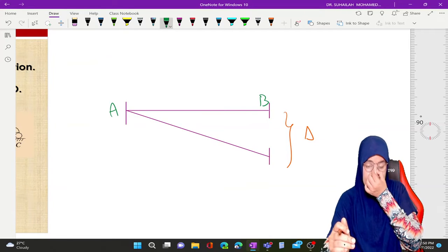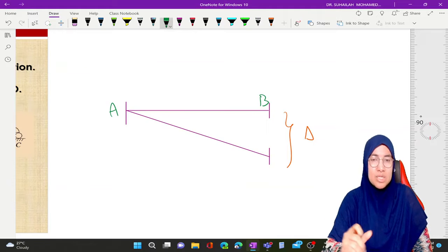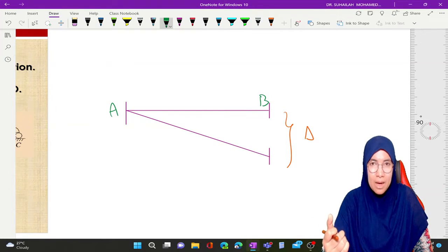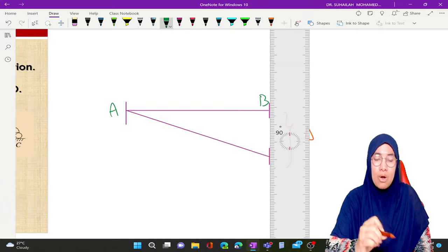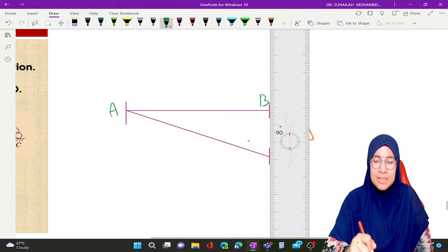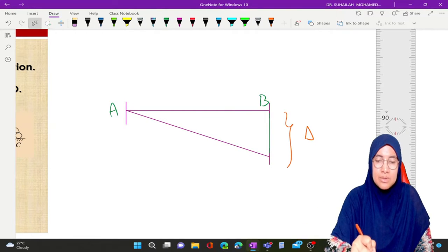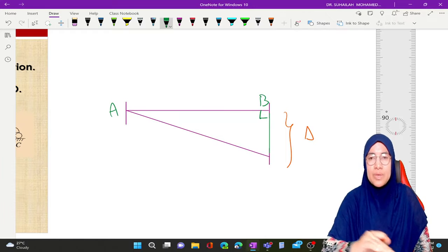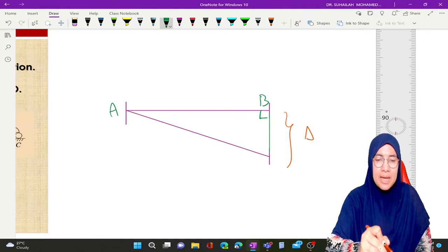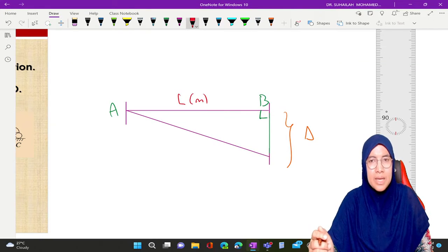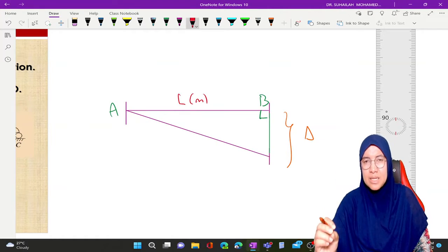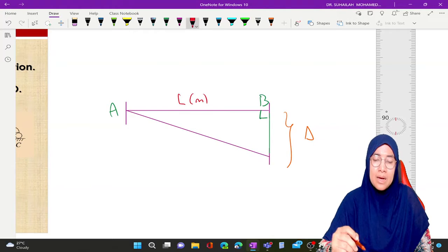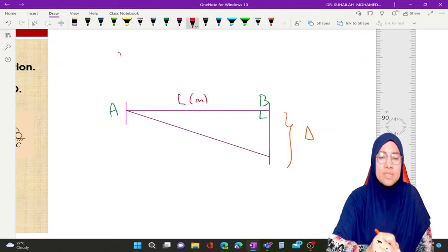And then we measure the delta, which is perpendicular to the member. It is easier if we complete this as one triangle, with the 90-degree angle, so that we get a full triangle. This is the length, span AB, and the vertical height is actually the vertical displacement. This delta occurs in a beam normally due to support settlement.